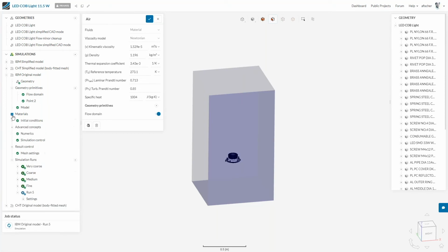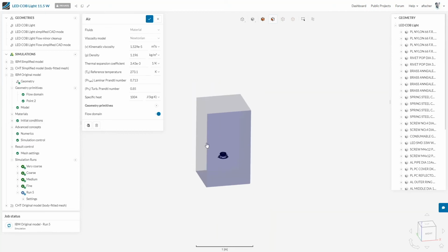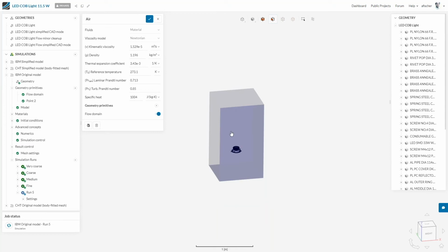Apart from that, the setup is very comparable and similar to what you know. So you've seen now materials. You might be missing the boundary condition setup. The reason for this is that currently this prototype is meant to be external natural convection cases only. Vuko mentioned that we're working on an internal prototype as well that will then contain all the boundary conditions. But for an external natural convection case, essentially all you need is a box.